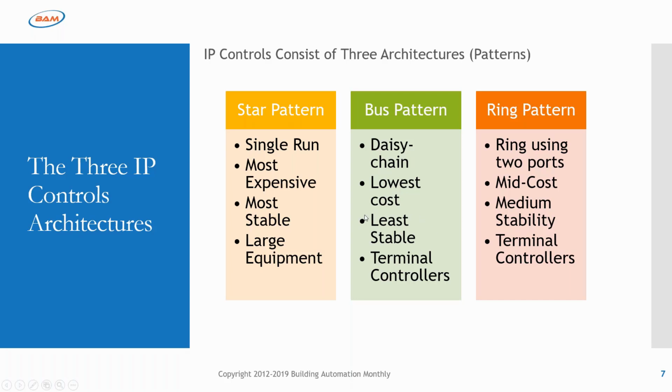I don't even know if that's the right phraseology for this, but basically, if you lose power, then what happens at any controller on most daisy chain patterns is because the Ethernet is coming into one NIC, one network interface card port on the controller, and then going out another. If you lose power, then everything downstream from that controller is dead. You can't read it. It's not like MSTP where you lose power at a controller and they're still electrically bridged, the wires are, and they continue on.